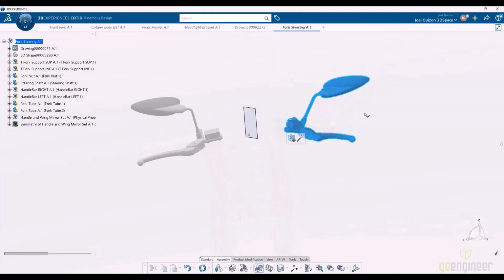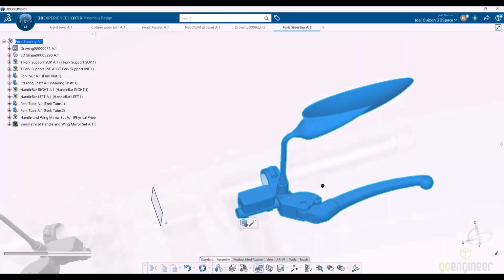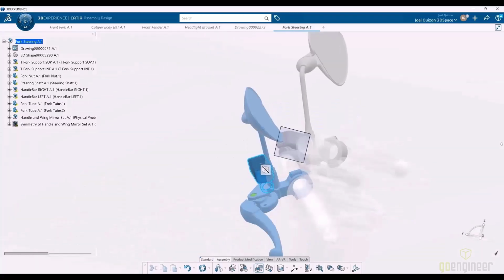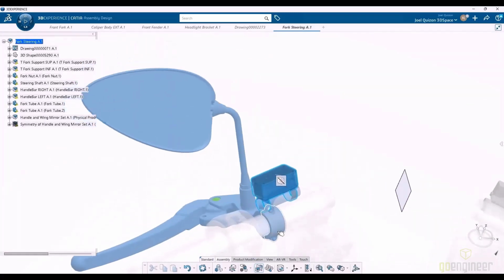And there you go. Now I'm in this interface that's really powerful. I'm able to just go in and pick a component. So this component, I want to use as the same reference. That's not a new part. That's not going to be a mirrored part. So I just select that. Then I could pick this component and use my shift key again to select this little subassembly. And I'm going to say that one is no symmetry. It's not going to be part of what's getting mirrored. I want to leave that out.